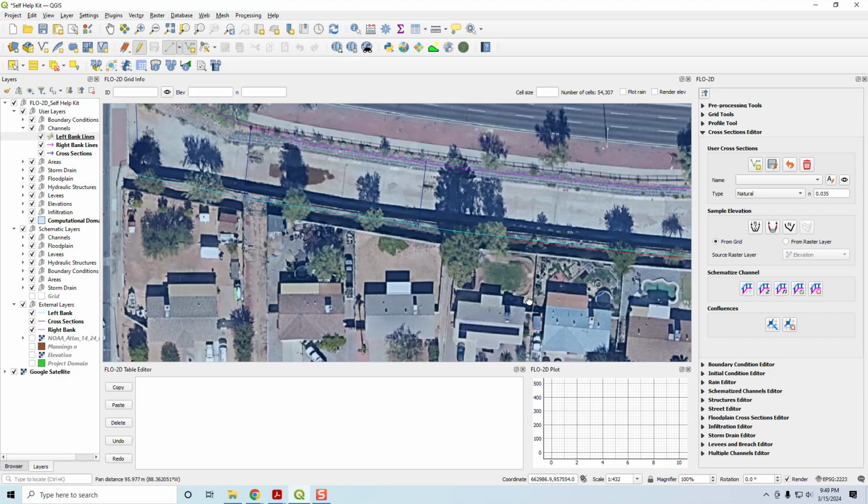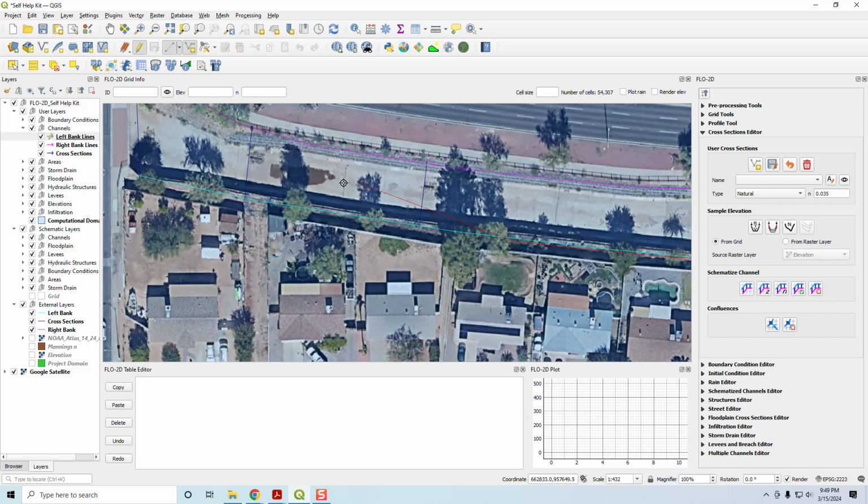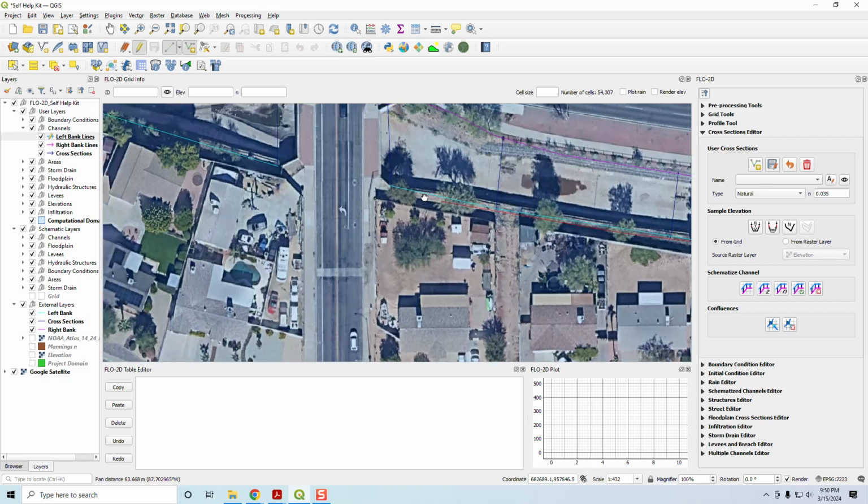What I'm doing is I'm left clicking. Now if you mess up, you just hit delete to delete the very last vertex that you put in. You can do that as many times as you want. If you really mess up, then escape will completely eliminate that line that you're working on. The most common thing you're going to do is accidentally right click and close the line, because your right clicking hand is on that and your left, and it's going to get tired.